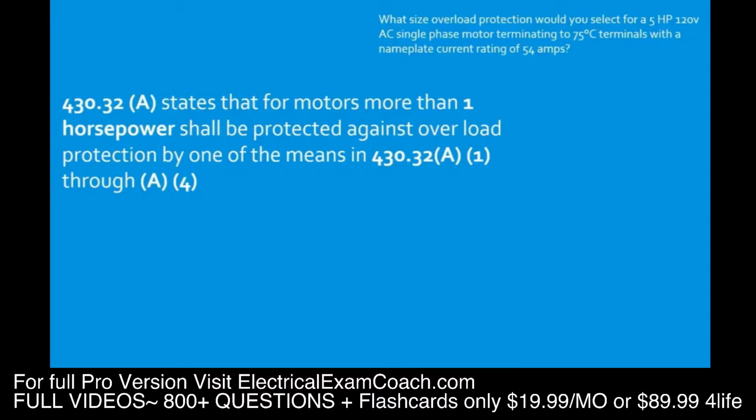So the only things that we have to focus on here are these 3 things that are listed right under there. Motors that are marked with a service factor of 1.15 or greater. And if you look all the way over to the right-hand side, it has a demand factor of 125%. The next one says motors that are marked with a temperature rise of 40 degrees C or less. That's at 125%. And then all other motors, and they only require 115%.